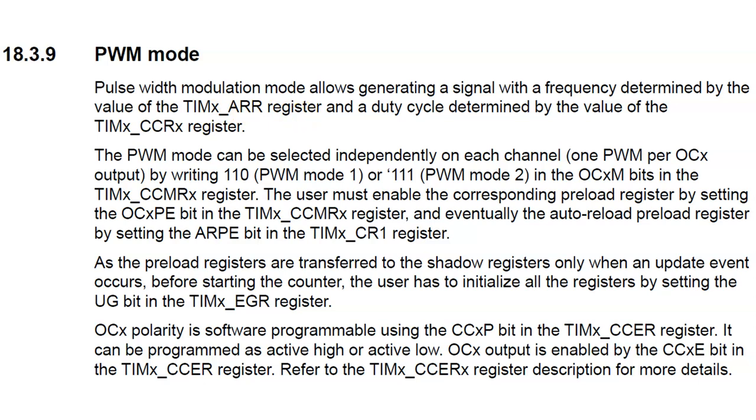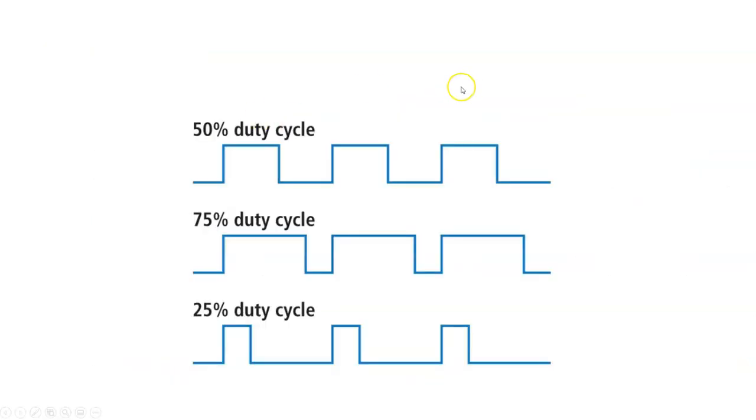In the past, we basically used ARR and the prescaler as a way to set the overall period, or the frequency at which we get an update event. In this case, we're going to use the ARR register to set the overall period of this waveform. What do we mean by the period of the waveform? This thing right here. If you look across all three pictures right here, they have the exact same period, from this high pulse to high pulse, this high pulse to high pulse, and this high pulse to high pulse. The value is the same.